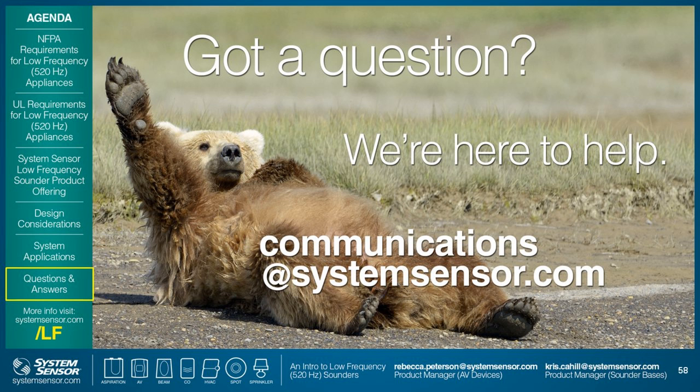Let's take just a couple more questions here in the time we have. The question about R occupancies. So are the only occupancies that need low frequency sounders R occupancies? In terms of, yes, at this point, yes. I think you're talking about like the hospitals and all those other occupancies. As far as I understand it, the only ones that have some direct requirements for occupant notification are the group R occupancies.